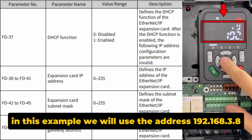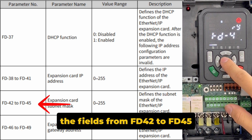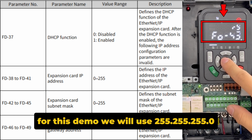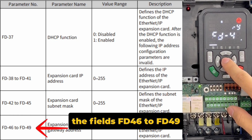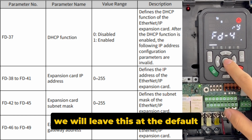In this example, we will use the address 192.168.3.8. The fields from FD42 to FD45 control each octet of the subnet respectively. For this demo, we will use 255.255.255.0. The fields FD46 to FD49 control each octet of the gateway respectively. We will leave this at the default.